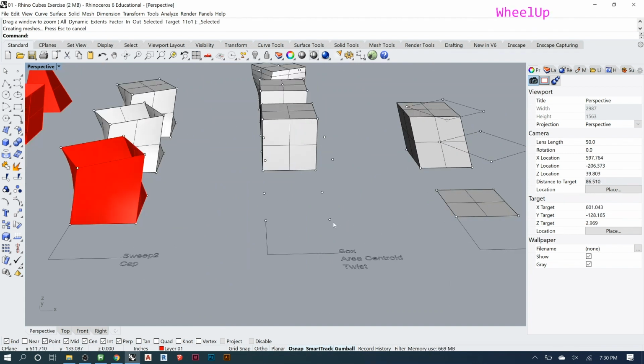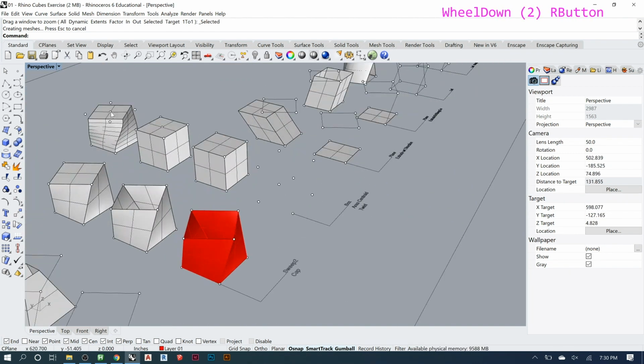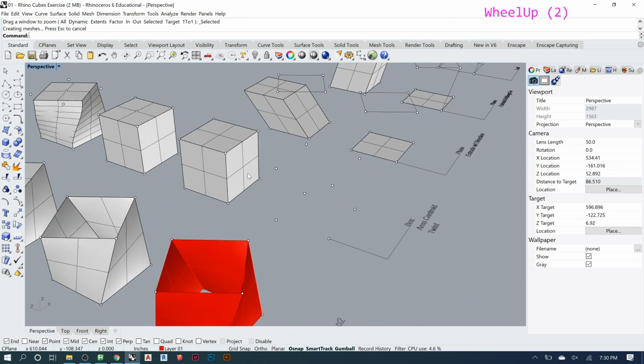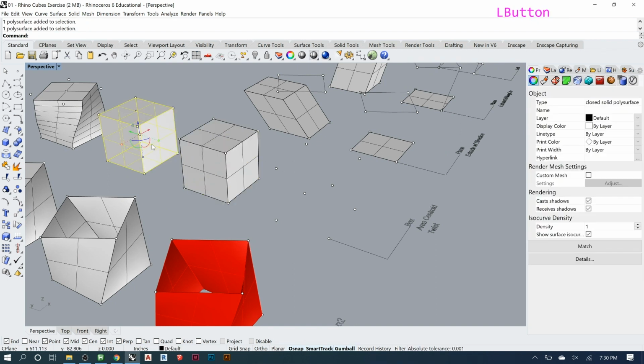Here, this one is kind of weird, but notice I've twisted the box. What I did here is I made a box, then I ran this command called AreaCentroid, which sounds like a weird robot, but what it does is create a new point in the center of mass of that object. Whatever your selection is, it will draw a point perfectly in the center. It creates a new point that didn't exist before, so that you can then start doing commands from that point.